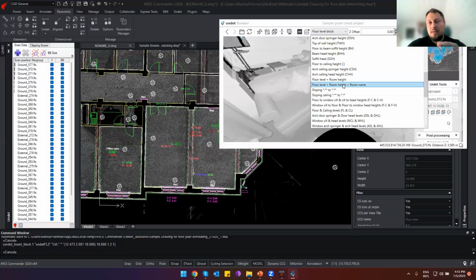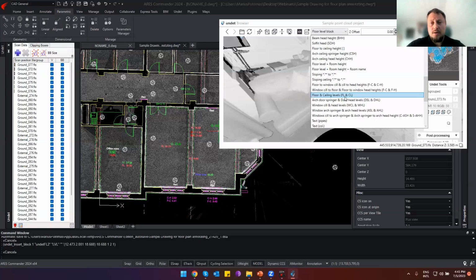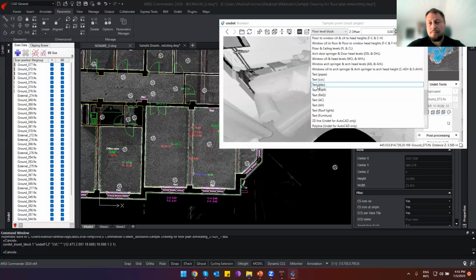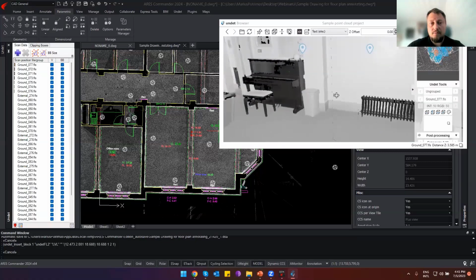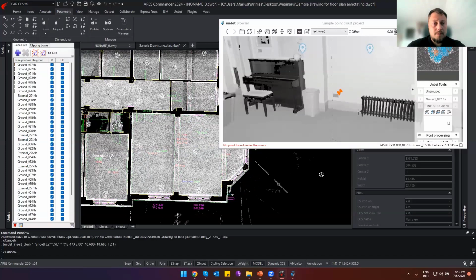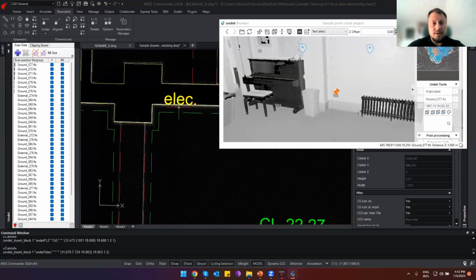So here you will find 50 prepared scripts just to understand how everything is working. And later on, you can adapt these scripts and blocks to your company style to meet your requirements, font size, layers. Maybe you need to create different annotation symbols or blocks. You can even insert text. You see there's a socket, one click, and the block is inserted.